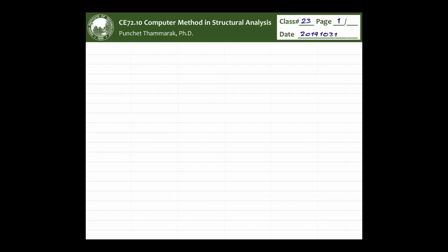So if you plot the deformation of your structure versus the load, you don't find any deformation until the load reaches the buckling load, and then you get infinite deformation. That is the loss of stability. The thing is that this situation is generally for where you have just the load alone on a single column, probably, or even for the frame.